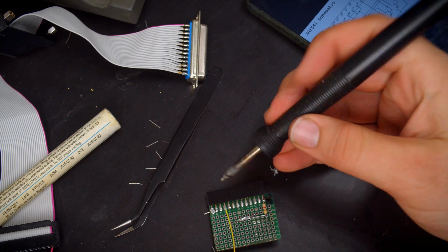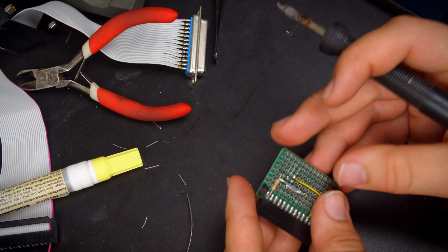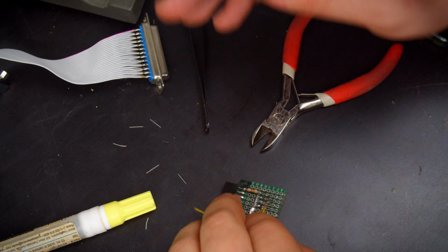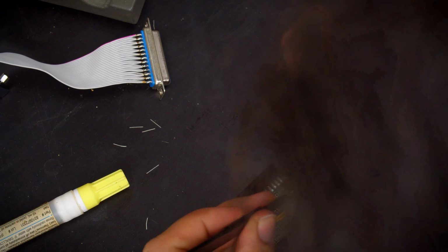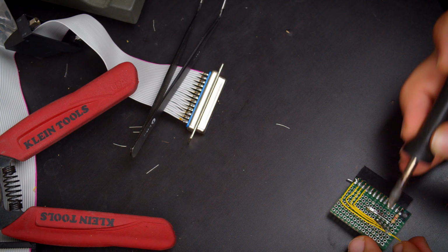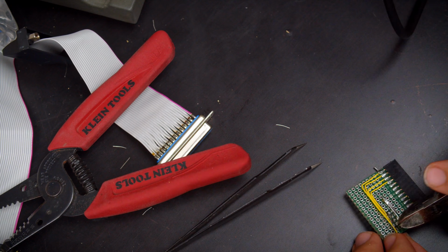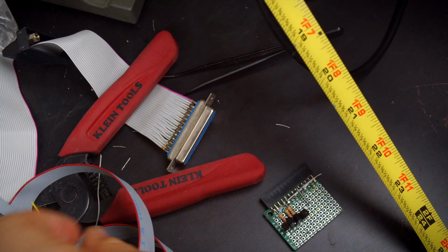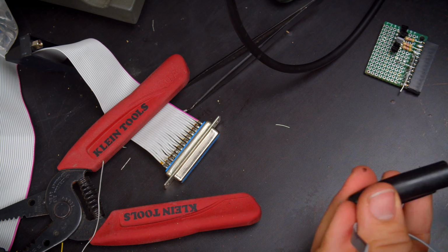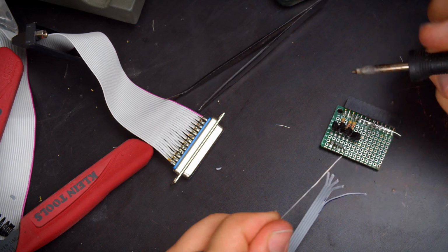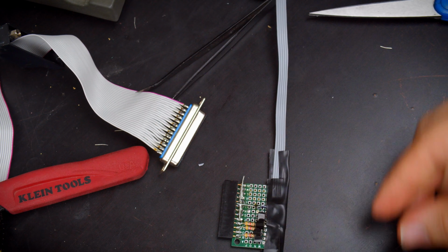Here, I'm using TO92 2N2222 NPN transistors, and really you're just looking for any small signal transistor, so you can get away with a lot of different stuff. They also specify 1/8 watt resistors. Again, this is probably from the original adapter because SMD parts come in cheaper, lower power options. I'm just using standard 1/4 watt through-hole resistors for the 4.7 k ohms here.